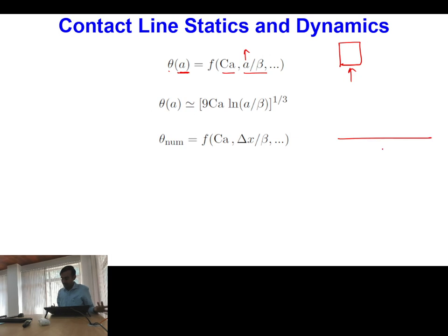Say, if you define that your surface is having a contact angle of 30 degrees and you have initialized a droplet something like this. So what will be happening? Now the droplet is forming a contact angle of 180 degrees. So with time this drop will keep on spreading and finally it will occupy an angle of 30 degrees.